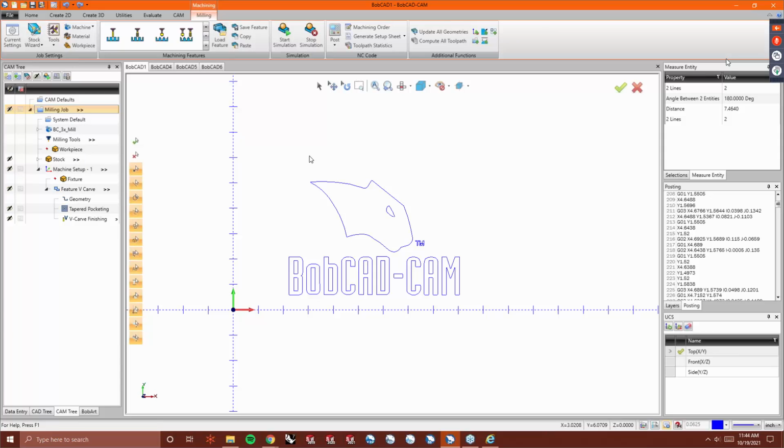But we're still here for any questions. Okay, so Kenneth asked, in VCarve, how do you get it to just trace the line without fill? You can't. It's not an engrave. You would use engraving if you wanted to just follow the line. Yep. It's a pocketing toolpath. You can't just cut a single line.